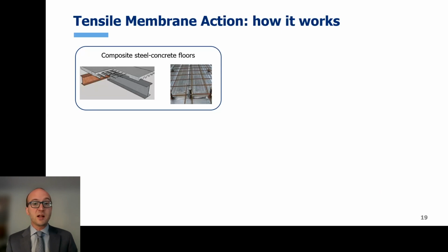Here is how tensile membrane action works. So we are talking about steel concrete buildings. We have steel beams that support a steel deck, and concrete is poured over the deck. There are studs connecting the beams and the concrete floors, so the system works as a composite. And note that it's important that there are also reinforcement steel bars embedded in the concrete. Different countries have very different practice in terms of how much reinforcing bars they use. These bars will be key.